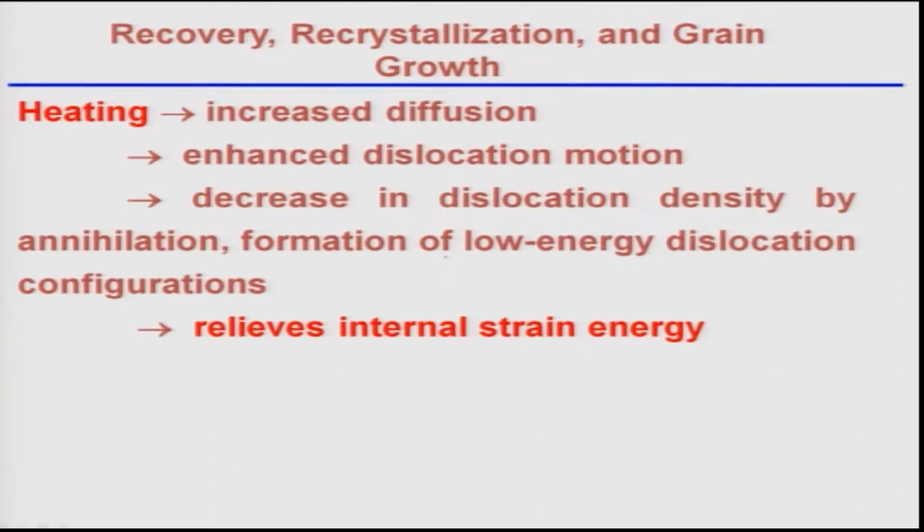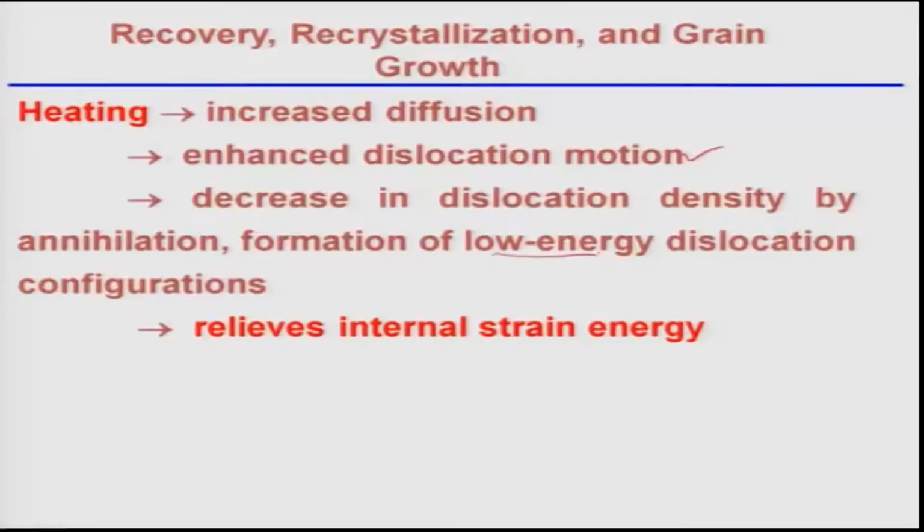Heating also enhances the dislocation motion; dislocations can easily move because of this temperature increase. Then dislocations will interact among themselves, they can lead to annihilation of dislocations, so the number density will go down, or they can lead to the formation of low energy configurations. All three of these things, that is point defect movement, dislocation annihilation and arrangement in low energy configurations, can relieve the internal strain energy. That is the basic purpose, because we want to relieve the strain energy.